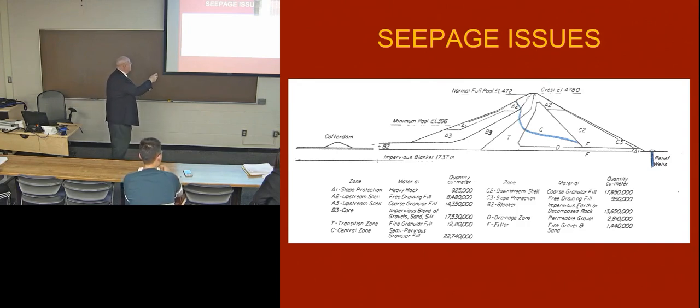So, this cofferdam is way over here someplace. And so we start our flow net at the upstream cofferdam, which is at the far end of the impervious blanket, and we start our flow net and say one flow line comes along like this, goes under the dam. But all in this region of impervious blanket, what do we have? Equal potential line, equal potential line, equal potential line.